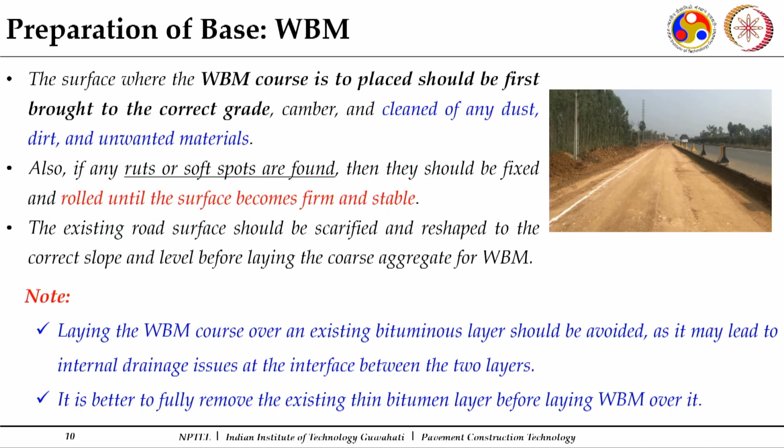So, in this particular one, as in case of other layers also, the important part is that the surface where the WBM course is to be placed should first be brought to the correct grade. Why? Because it may happen that you have constructed a subgrade top or a granular subbase course a few days back, and there was a time gap before coming up for the next layer.